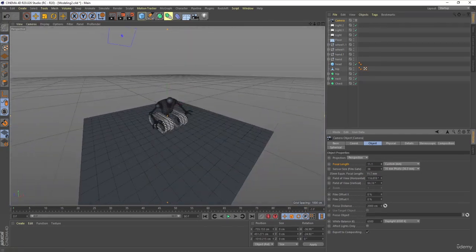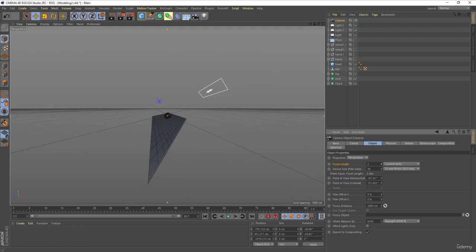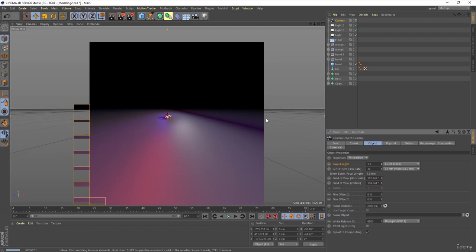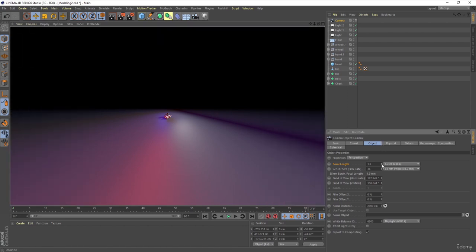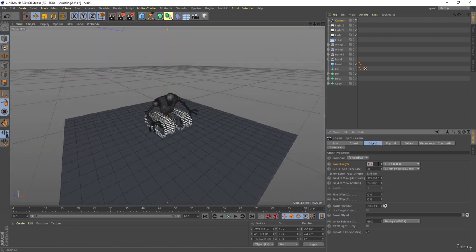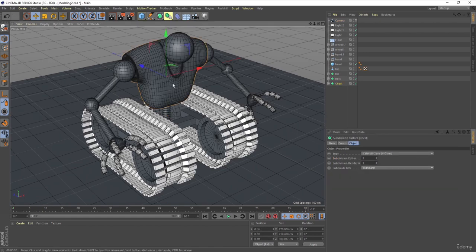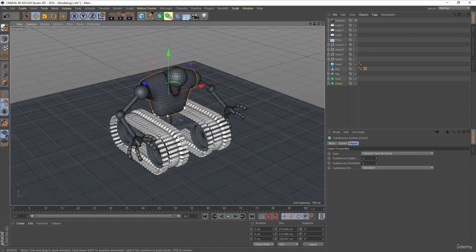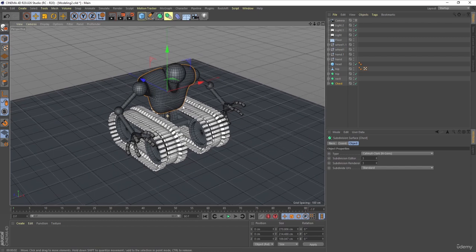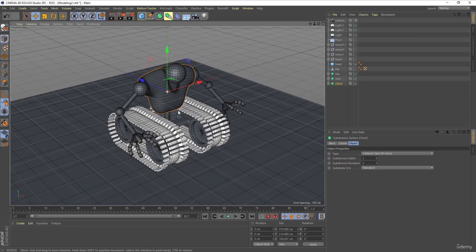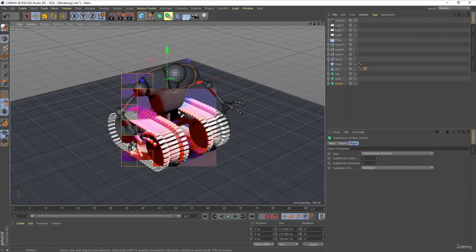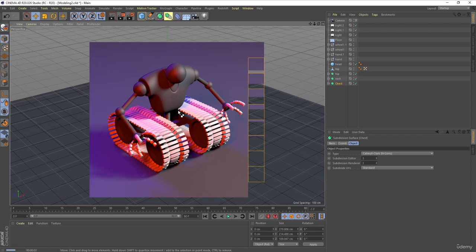If I decrease the value, as you guys can see, we will get something like this, which definitely we don't want. If you hit Ctrl R over here now, as you guys can see, we will get different results. So I don't want that, so I'll increase it. Right now it's 36, so let's make it 50 and select this and press S and let's zoom out a little bit. Okay, so this is how you can create the scene. And now if you hit Ctrl R you will get this kind of result.